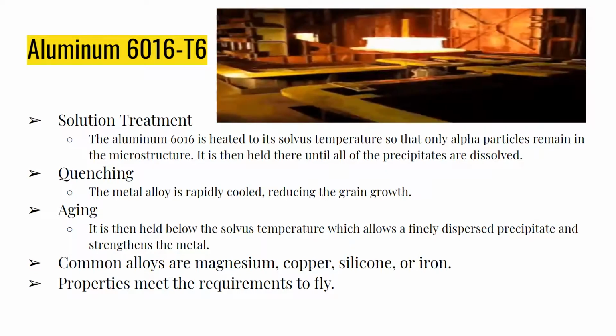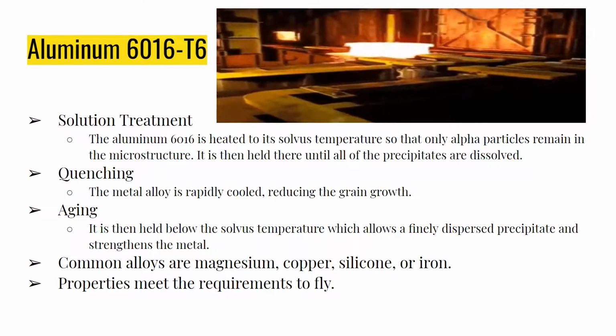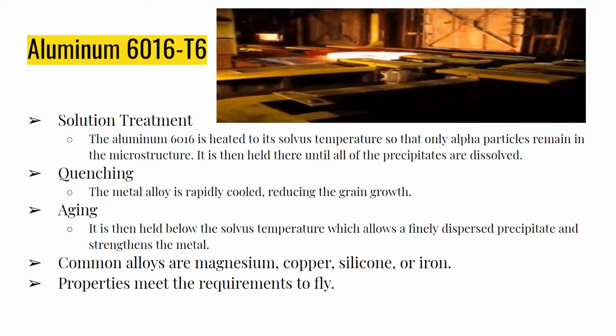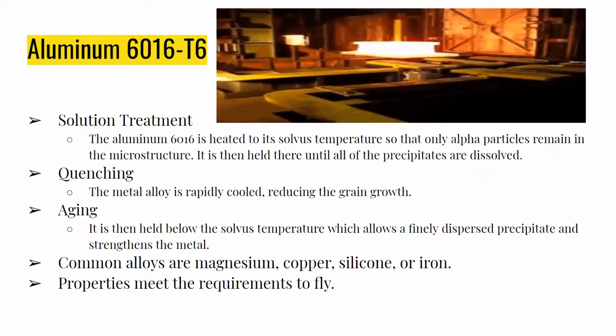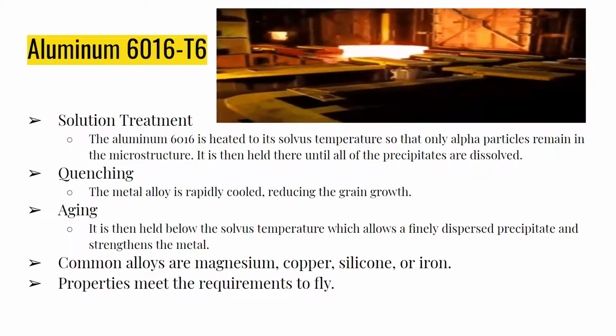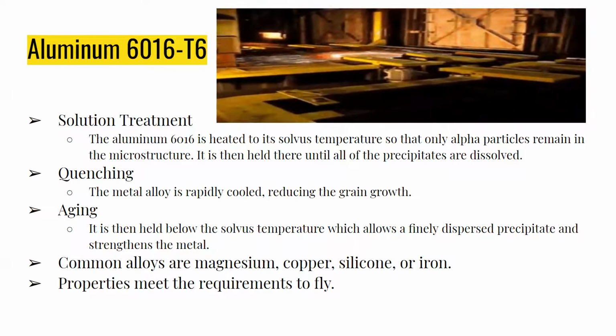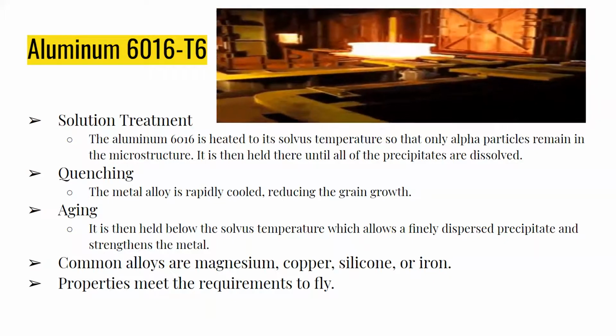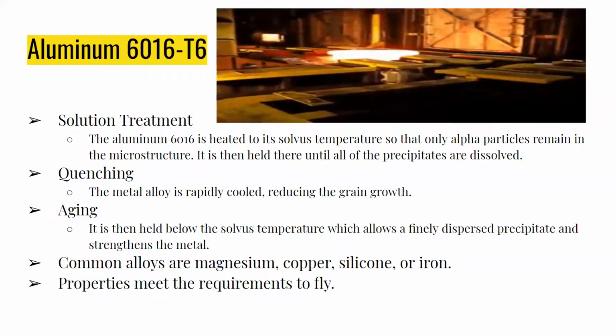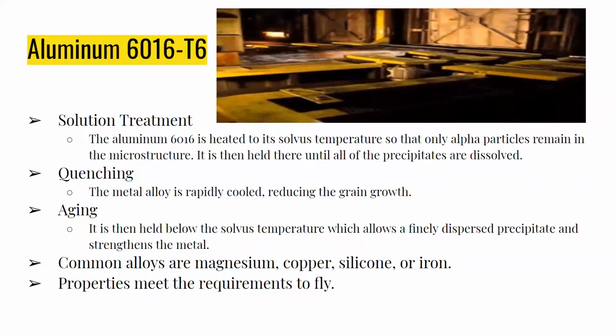It has an average elastic modulus of 69 GPa, a Brinell hardness of 60, an elongation at break of 11%, a tensile strength of 280 MPa, and a yield strength of 210 MPa. The material has a low density of 2.7 grams per centimeter cubed, which meets the low density needed to fly.